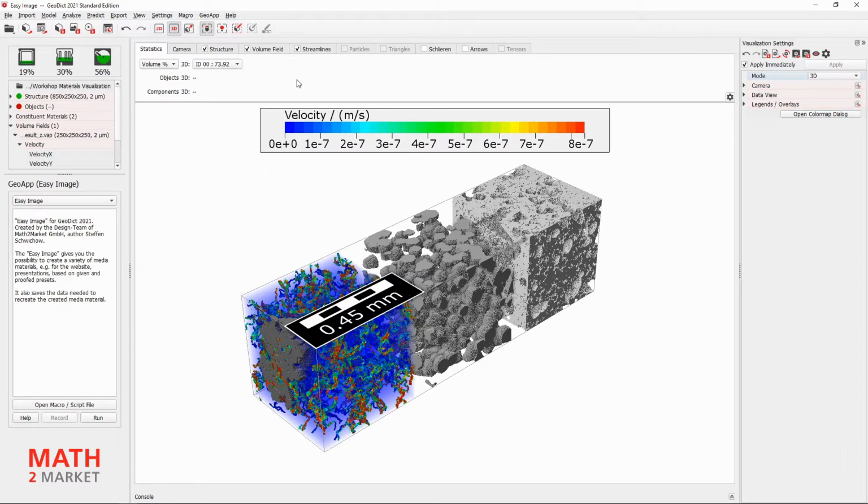To account for the fact that the filter gradually clogs over time, FilterDict lifetime uses an iterative approach. First, a flow field is simulated for the clean filter medium. Then a so-called batch, a subset of the simulated particles, is injected into the filter medium. Some particles will get stuck inside the medium and clog the filter. Then for the partially clogged filter, the flow field gets recomputed and the next batch of particles will be injected. This process is what we are going to visualize here.